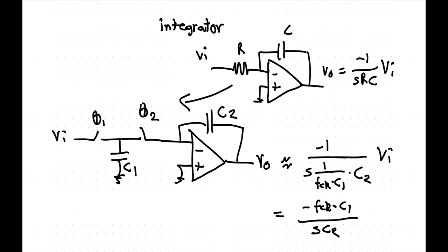So this is a discrete time system. That means that me doing this one here is not correct analysis. I've been really naughty because I put in a clock frequency and used the S domain. This is okay as long as we're looking at frequencies much slower than the clock frequency. But if the frequencies are not much slower than the clock frequency, then we've got to analyze it in a different way, looking at what the discrete time system is.